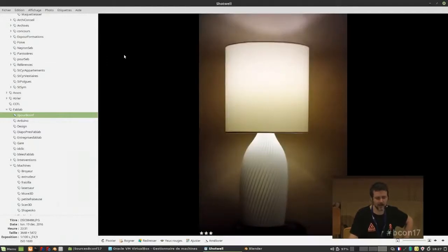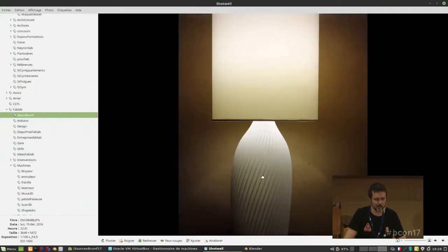So these are things I designed in Blender. I think you know how to design it; there is nothing impressive in the design. You take a curve, a circle. Then you select one every 2 points, there is this in the select menu. And then you scale so that one every 2 points goes inside, and you have a flower. Then you extrude it, you take the top, tilt it and scale it, and you have your lamp.